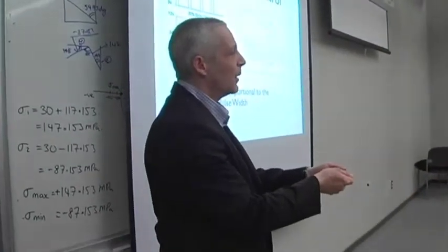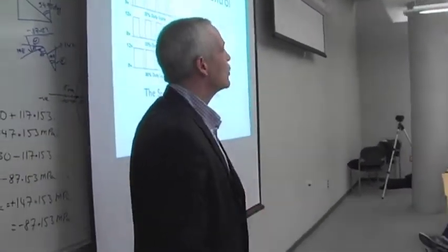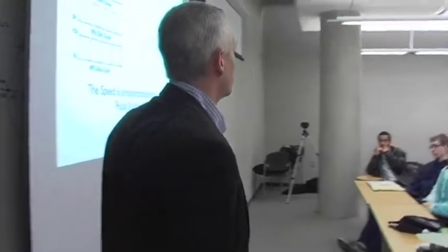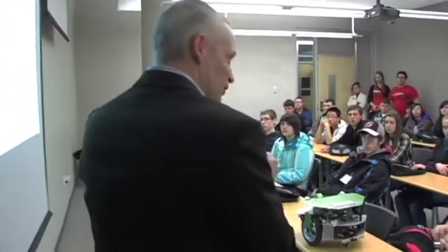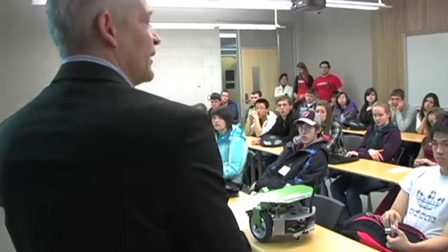I mean, with a motor, you can take a battery, just hold the battery to the motor, and it just turns, but you have no control over it. So how can you control the speed of the motor? What you do is you connect it, disconnect it, connect it, disconnect it, and the amount of time you have it connected tells you how much energy you actually put into the motor.